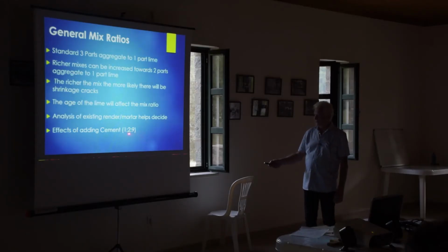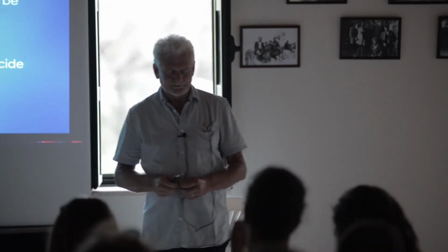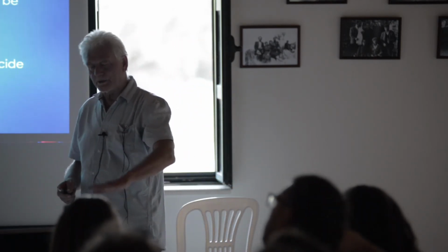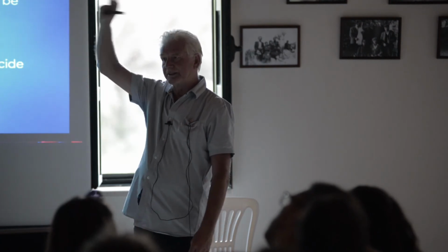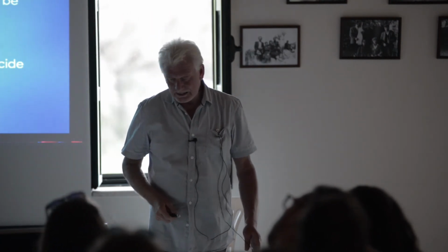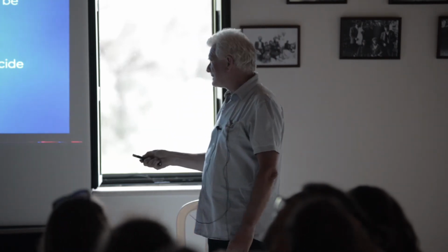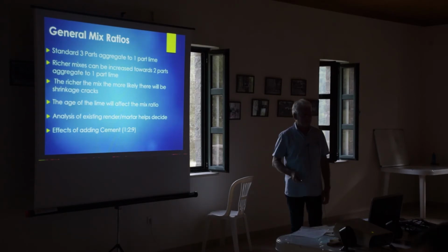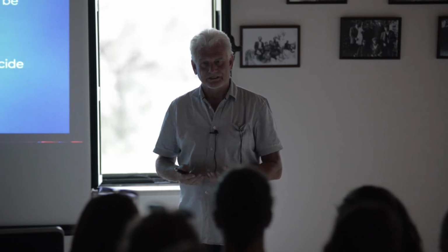That ratio is still 3 to 1. But what they were suggesting was that in certain positions on a building, let's say at the lower part, where there's danger of water penetration, danger of rising damp, and up on the very top, let's say on the chimneys, where there is also more than normal weathering, they were recommending this sort of mix on the basis that they felt that the addition of cement would firstly move the chemical set on a little bit, and they would get earlier protection.